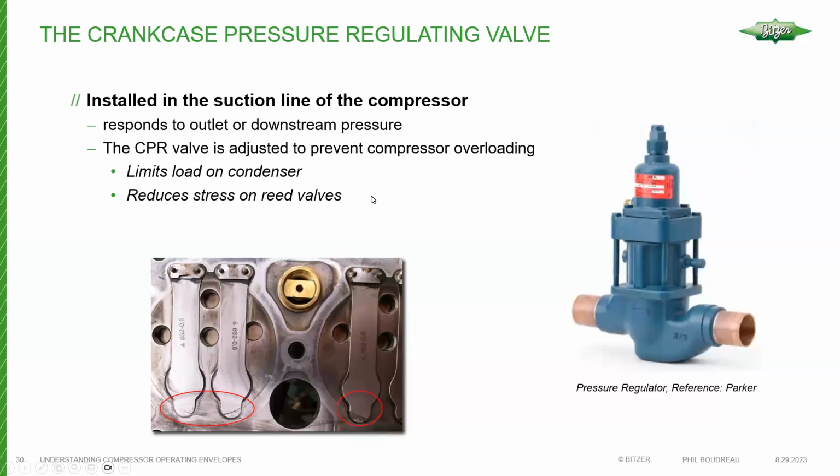The discharge pressure is going to be lower, which reduces the stress on the reed valve. Some of the things we'll see happen to reed valves when they become stressed due to very high pressures and rapid oscillation due to high mass flow rates is basically hammering of these valves, where they drop into the cylinder and rest against the suction seat, which is supported by a machined out portion of the cylinder wall that allows this suction reed to sit in it. So we're looking at the bottom of the valve plate here. Over time, these can experience so much oscillation and hard work and stress that those tips can actually break off.